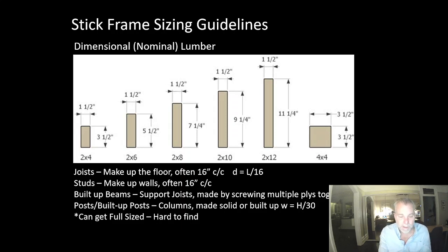Studs for exterior walls are almost always 5.5 inch 2x6. For interior walls, they're typically 2x4 or 3.5 inch studs at 16 inches on center. You'll always be credible if that's what you assume.